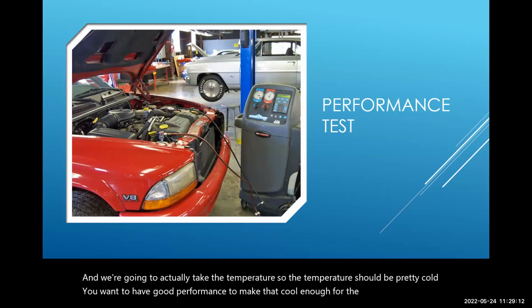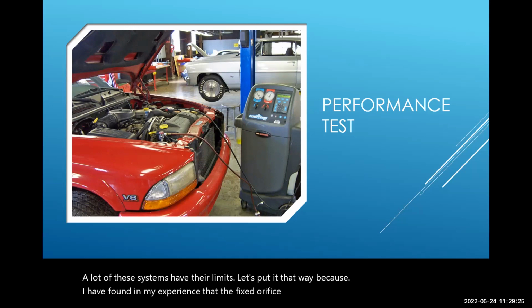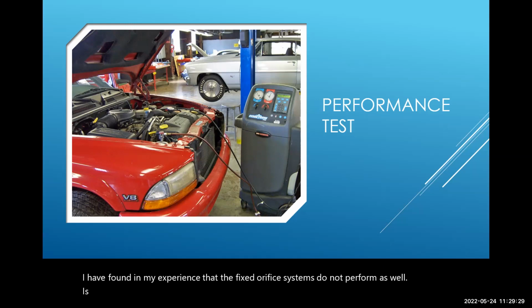Now, granted, a lot of the systems have their limits. Let's put it that way, because I have found in my experience that the fixed orifice systems do not perform as well as the expansion valve systems do. So that's something to take into consideration when you're doing your actual temperature testing, your pressure testing, and stuff like that too.